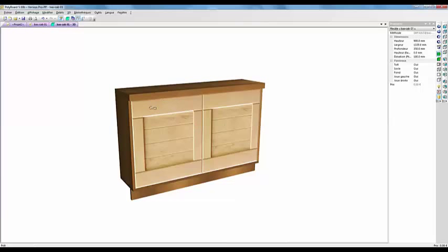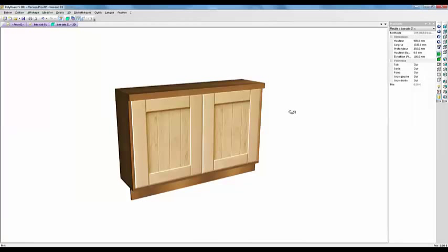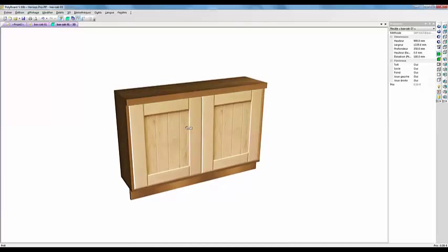We can see that they're actually not aligned. They're not upright. The doors have come in horizontally. It would be pretty good if they were vertical. So let's go into each panel here, and in the materials rotation, let's just add 90 degrees. So I go into this one here, materials rotation, 90 degrees. Now when I go into our base cabinet, they've turned the two doors by 90 degrees, and we have two doors which have come straight off of Google, and we've just put them into our cabinet, which is pretty neat.